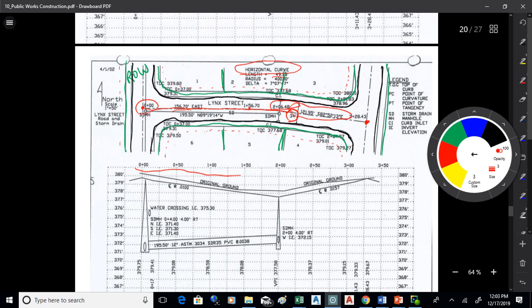Now down below what we have are the stations and a nice even grid every 50 feet. The grid itself is broken into 25 feet horizontally. It's labeled every 50. So that runs its way across the page. Then we have the elevations above sea level, typically at a different scale than we use horizontally. We like to exaggerate that vertical scale so we can actually look at these maps and see which way things are sloping. That helps us to understand grades and how water would flow and that sort of thing. So that's on there as well.